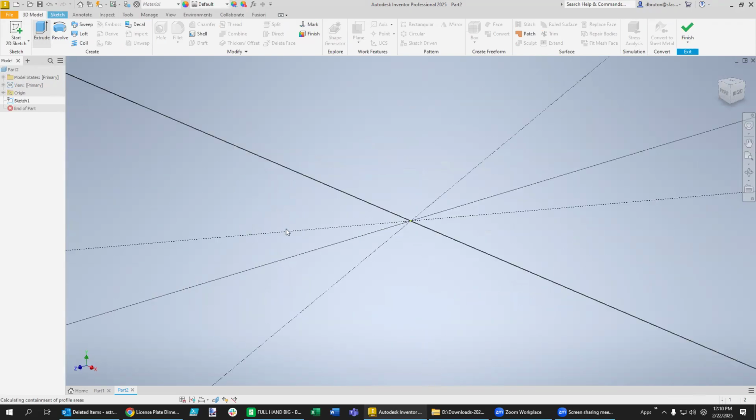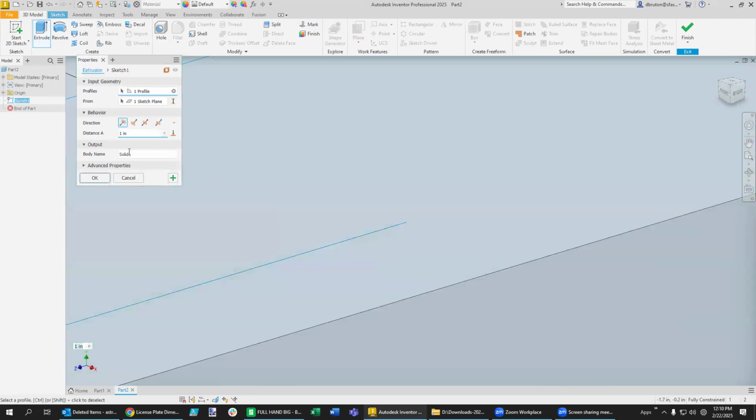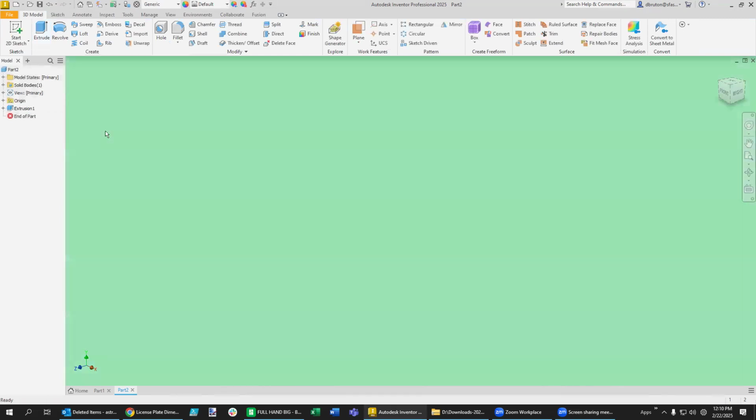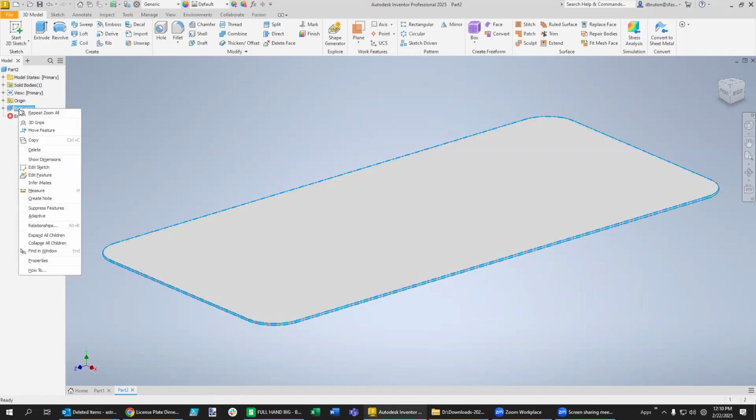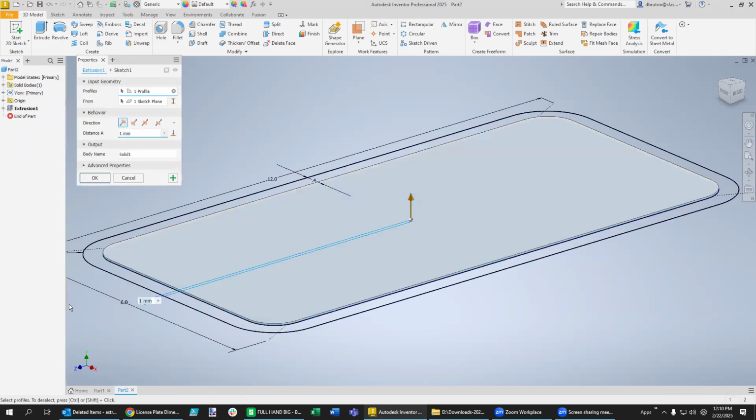And we can just make the extrude in the middle 1 millimeter. So you can type in 1 millimeter like that, and it will basically put in 0.038 on the thickness. Now, one of the things I should have done here is only focused on the middle so that I can have a little bit more raised effect on the outer border. Or I could put like a groove in there, but I'll just raise it up just a little bit. So we're going to say edit feature, and we want to make sure that we only selected the middle. Well, it looks like I did that.